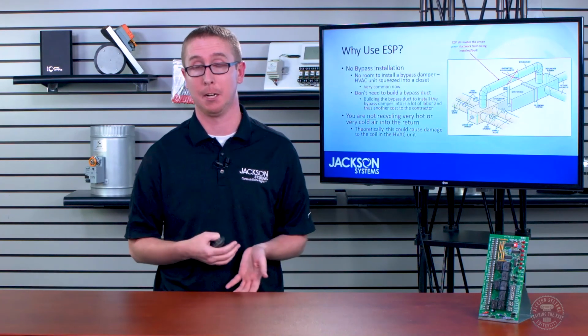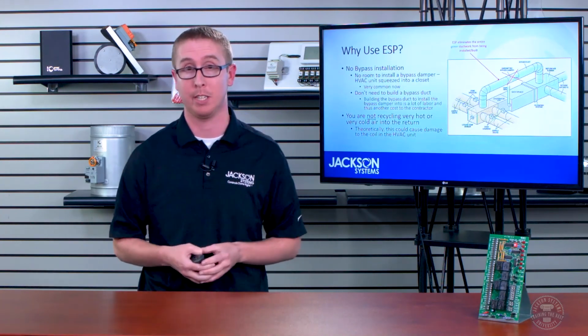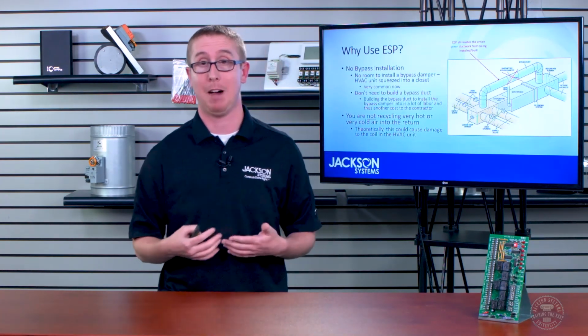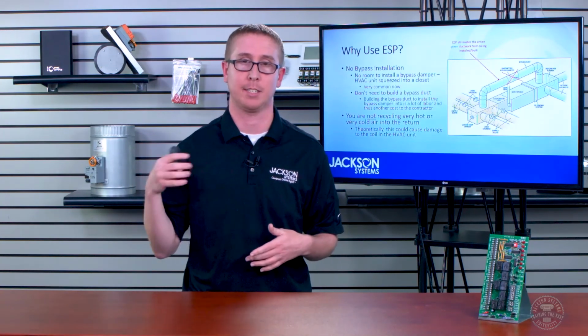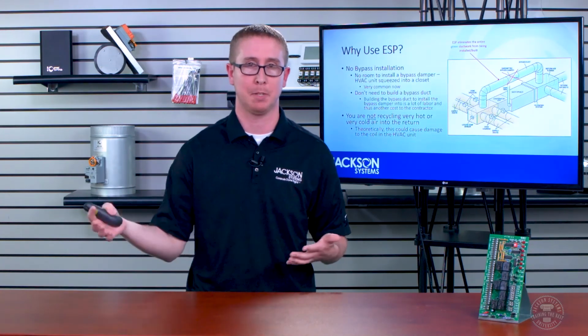That's the biggest reason why people go to this system. The second benefit is that you're not recycling extremely hot or extremely cold air into the return ductwork. Again, a bypass damper is going to take the air from the supply and dump it into the return. If it's doing that consistently enough and that air is extremely hot or extremely cold, there's potential there that it could damage the HVAC equipment.